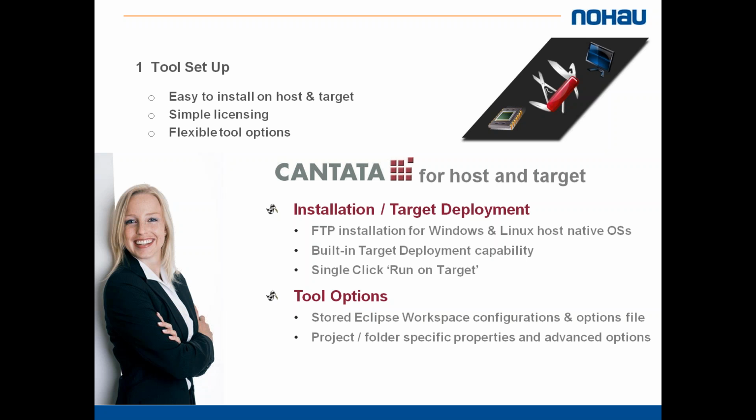To install on your target, it's a little bit more complex because you need to adapt the drivers for the test harness so that it can load the test and communicate the results some way. So your target needs to have some kind of communication possibility. Cantata is basically configured for Eclipse, but can be used under Microsoft Visual Studio and other environments as well.